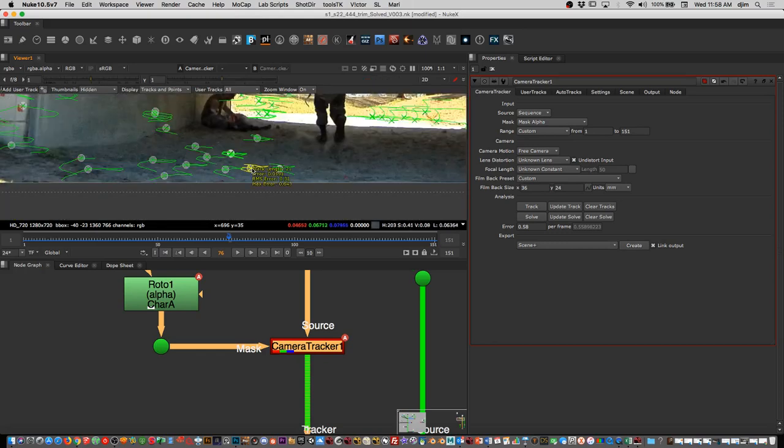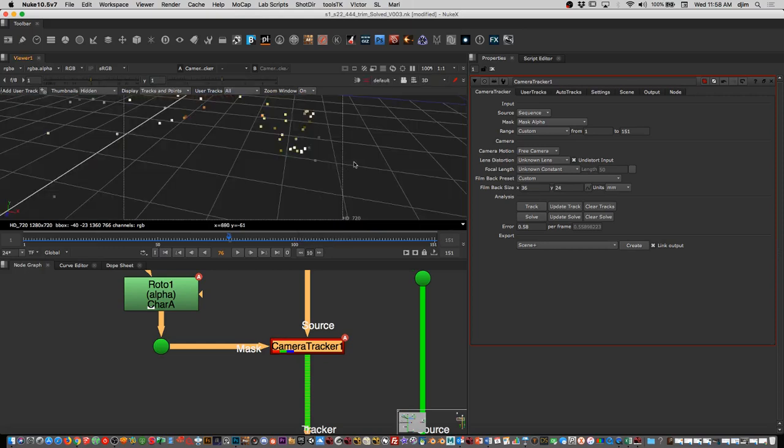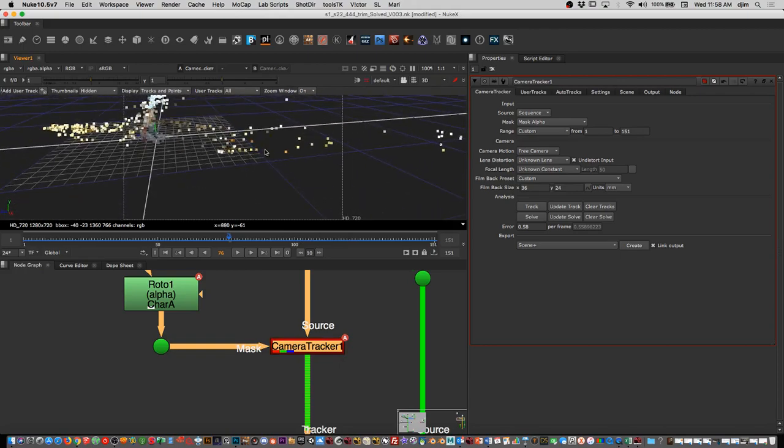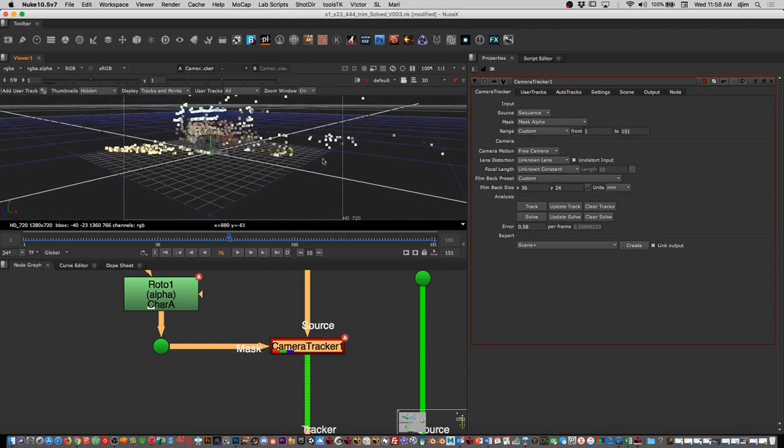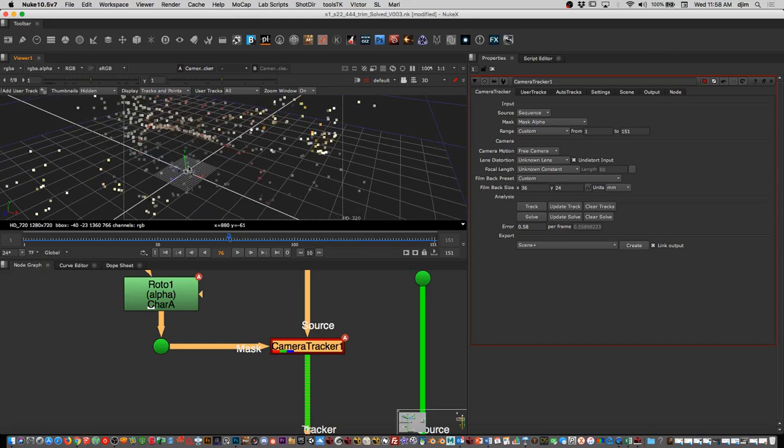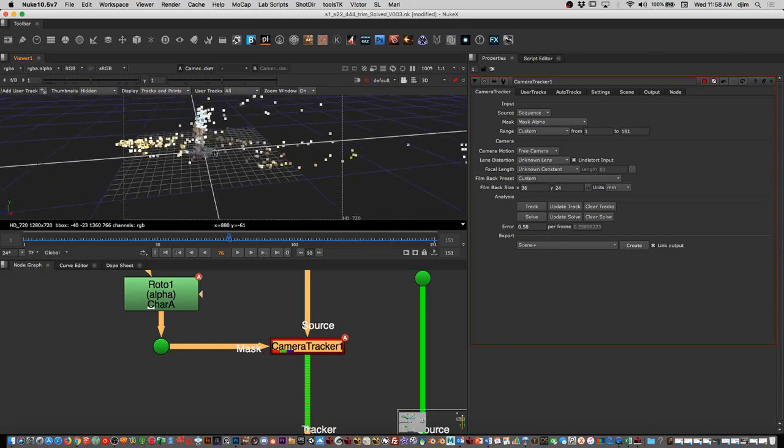So I'm going to hit Tab. I'm going to right click, ground plane, set origin. And that's how we actually assign the coordinate system. So right clicking, setting to origin. Now, as soon as that is set up, if I hit Tab, the whole world moved and set up that point as my origin. Now, the world's still slanted.